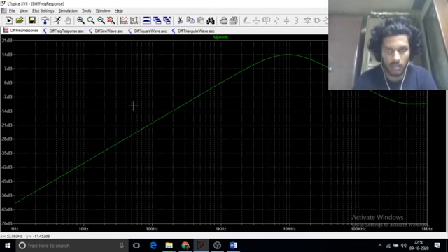As you can see, it's first constantly increasing until it reaches a value of around 14 decibels, 14.1 according to my one. At 10 kilohertz is the point where it reaches the peak around, and 1 kilohertz is approximately the point where it reaches 0 decibels.